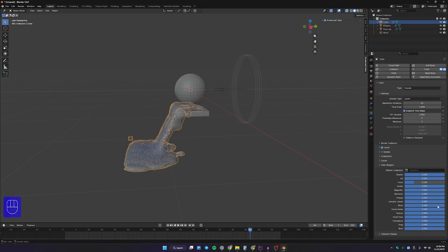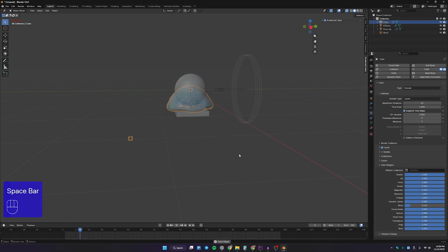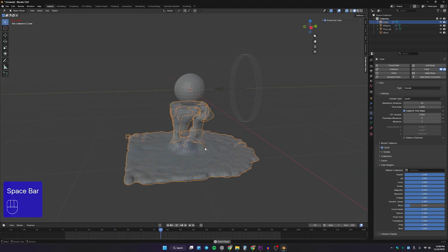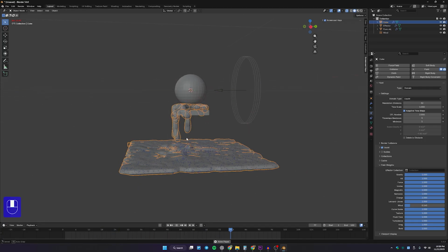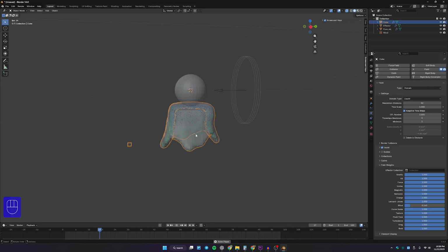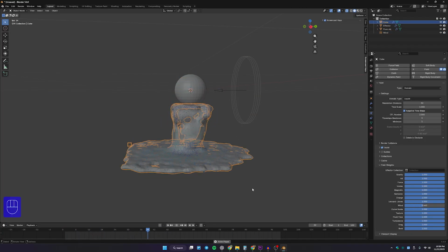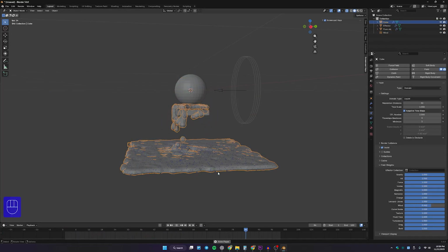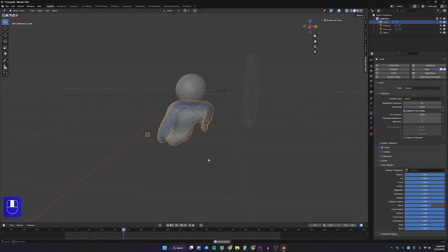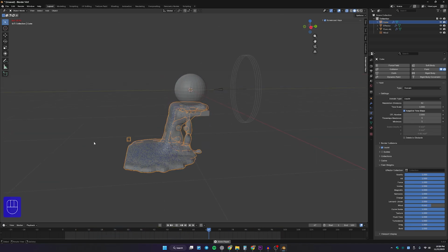Maybe, yeah, this one, the wind one. I'm sorry about that, but if I reduce the wind force influence, we can see that my flow is flowing with only a little subtle movement because the influence of the wind is really low. Now you can increase that, and you can see there is a little bit of force in this direction, right?